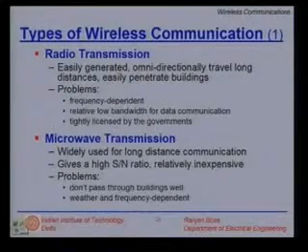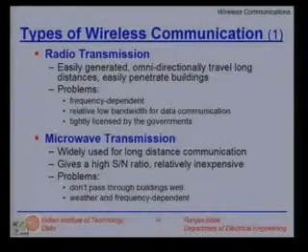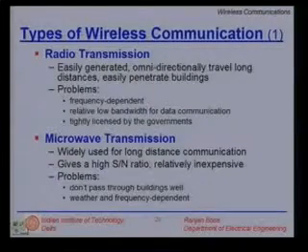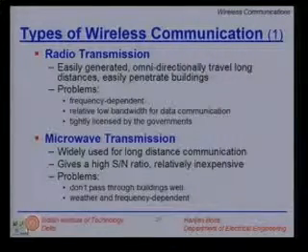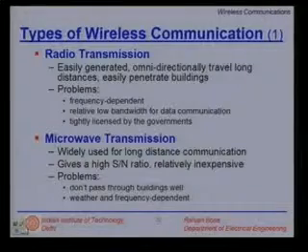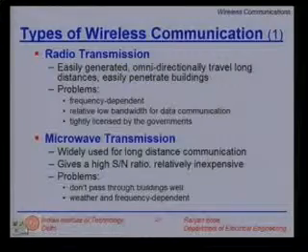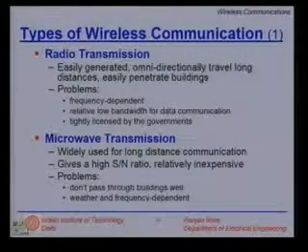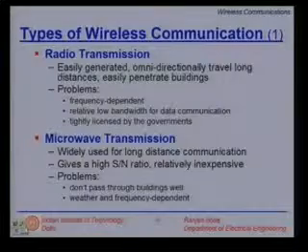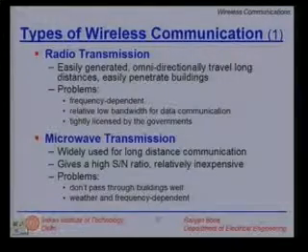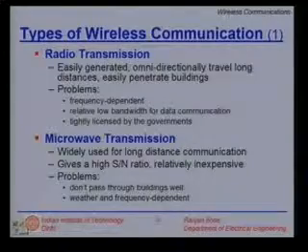So the next method of wireless communications is to use microwaves, which is at a slightly higher frequency, smaller wavelength. Clearly, you can use them for long distance communications. Given a high signal to noise ratio, they are relatively easy to make, manufacture and use. The associated problems are they do not pass through buildings very well. Consequently, microwave links are point to point line of sight.